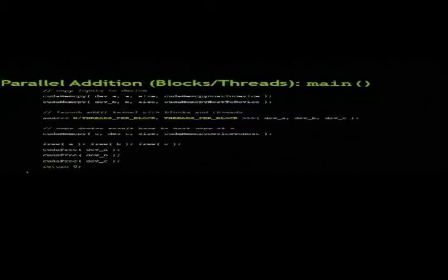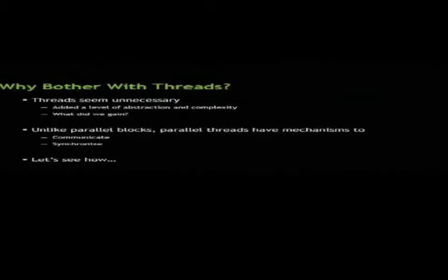So basically, this was the question that I tried to answer earlier. Why do we even need threads? Why don't you just give me a bunch of blocks and I'll use those blocks? This is where it becomes tied to the GPU architecture somewhere. If you look carefully at the GPU architecture, each streaming multiprocessor has some number of cores, and then it has some shared memory with it.